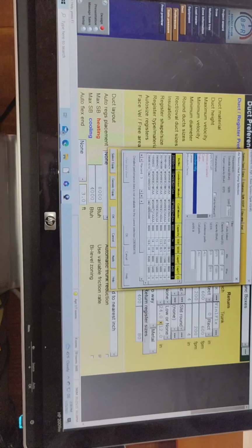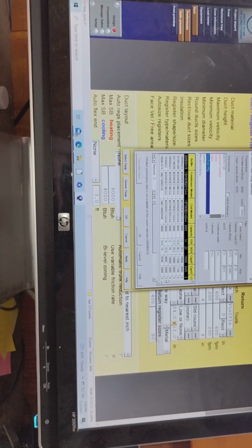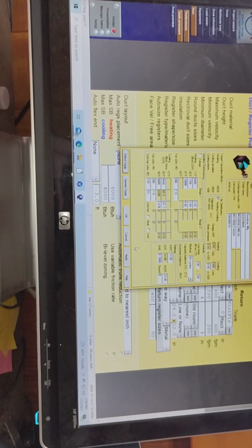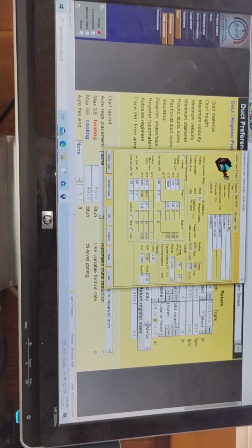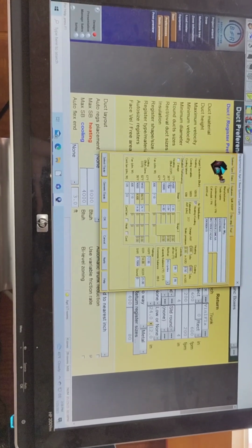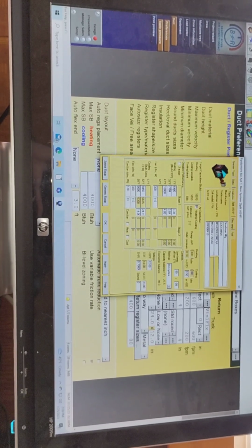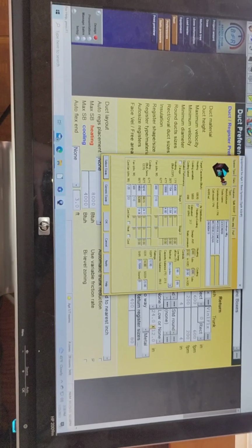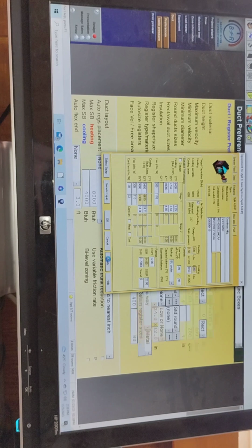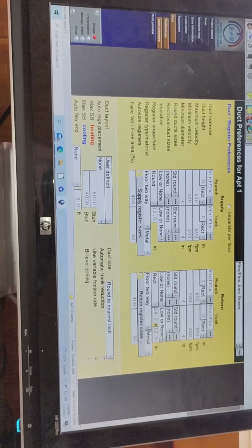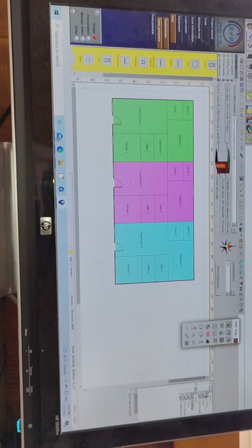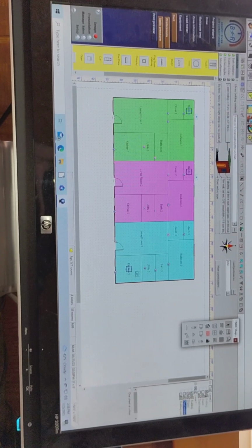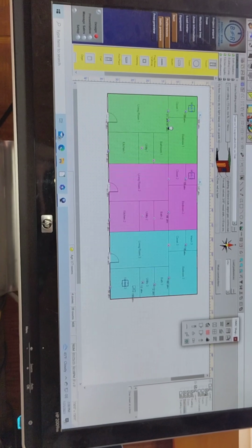So I'm just going to select one of these to keep the video moving here, and then I'll go back and adjust it once I have all of my stuff set up in it. As you can see, I selected the equipment. It fed in what the different BTU ratings are, what the fan's running for CFMs, all of that type of stuff. So we'll apply it. We'll go OK. We'll go back to our drawing. We're going to let the duct show up. We're going to show the duct notation.